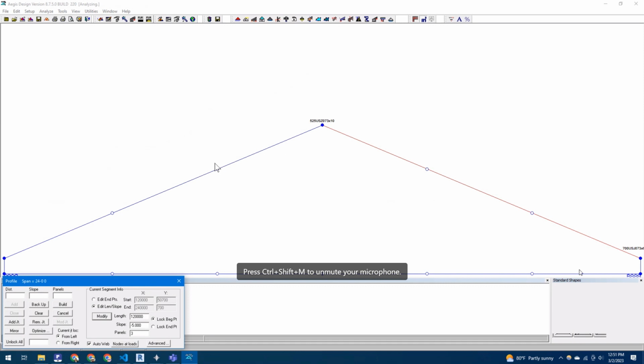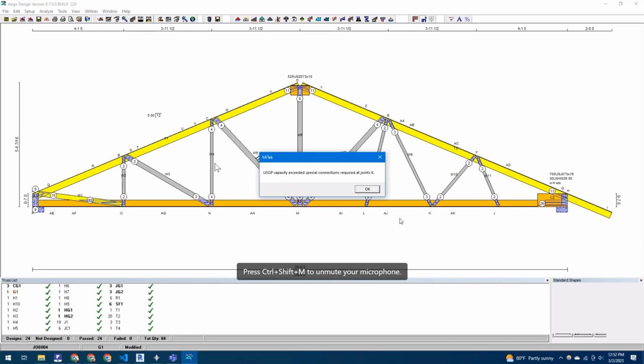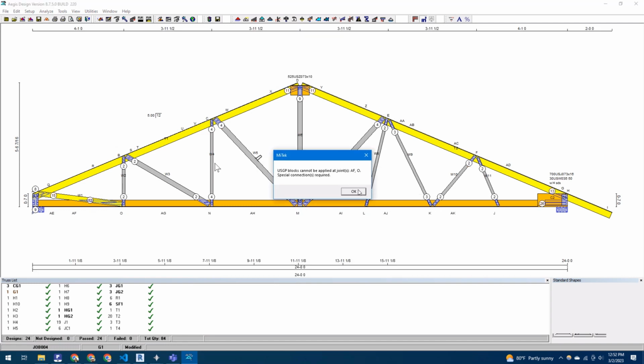So click on that. Click on the bottom chord. You tell it to add a joint. All right. Select one of them, probably the one like that one. Change that number to match where they wanted you to put it. I don't remember what it was. Yeah, that should be close enough. It's pretty close, yeah. Like build. And then it'll finish. Click OK.